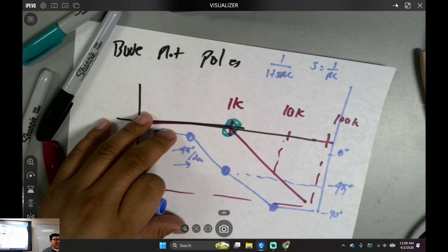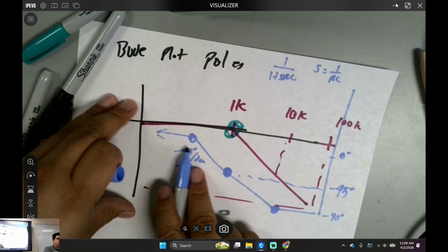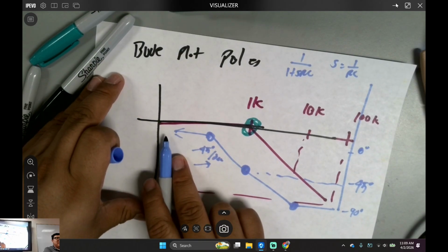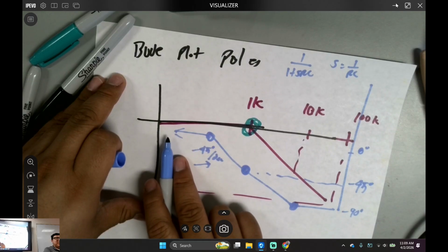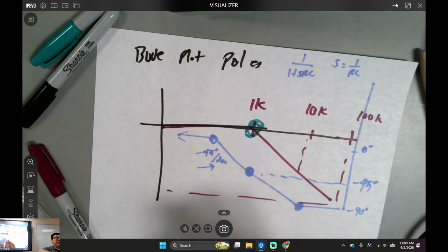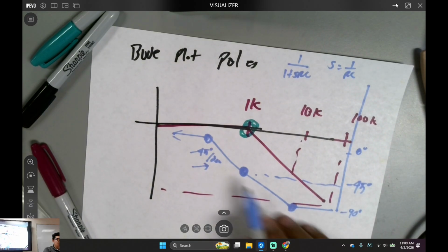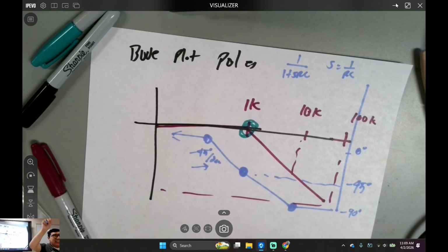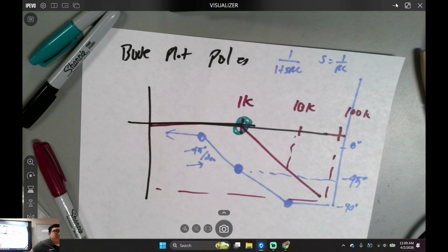So what I'm trying to say is, you see how for a capacitor, if the frequency is super low, we have 0 degree phase shift, correct? It's an open, and we get 1-to-1. The output and the input go up and down like this. There's no phase change. Can everyone agree with that? 1-to-1 power, 0 dB, V out equals V in. But now, do you see how we start increasing the frequency, and you see this impedance? This is why I think the phase response is super important.